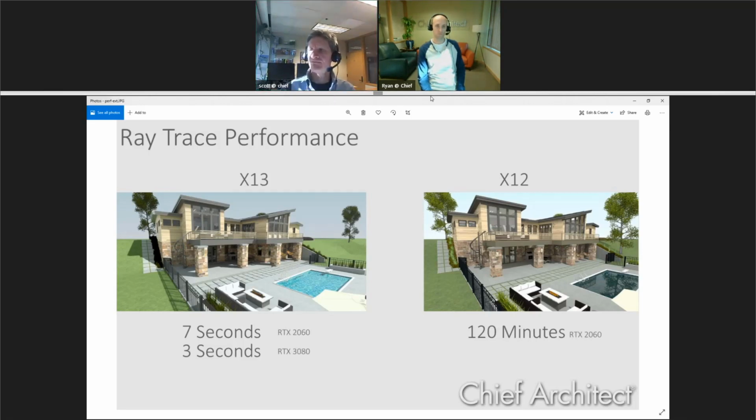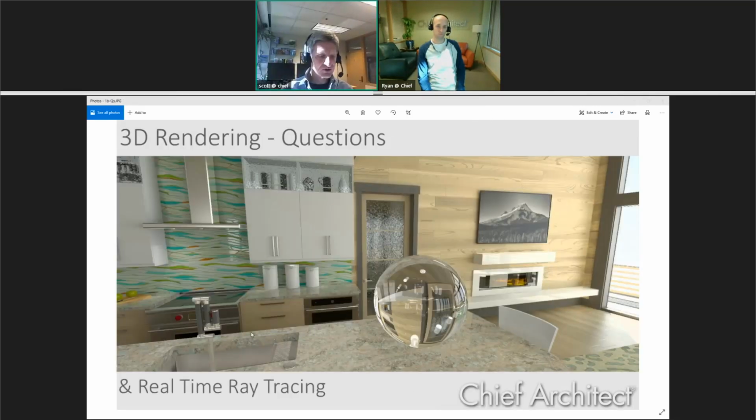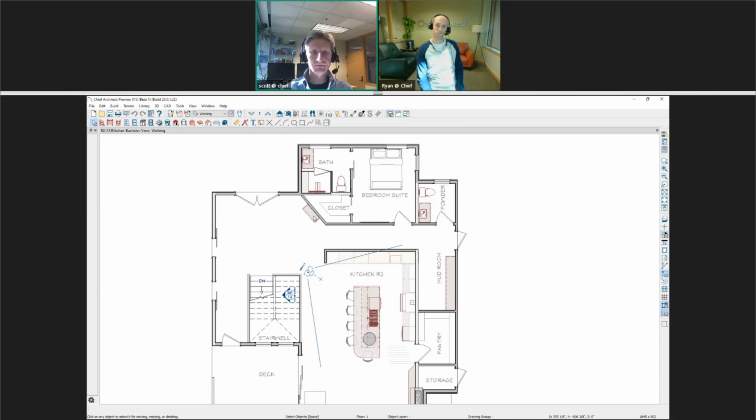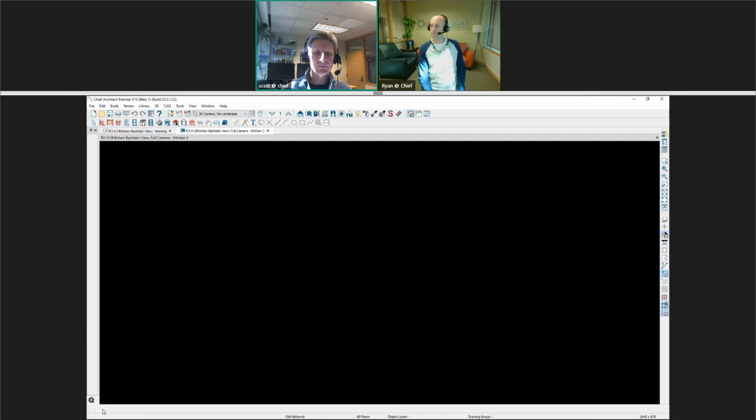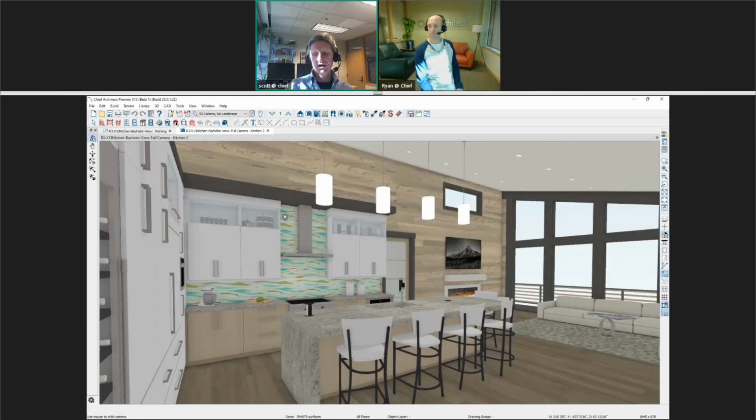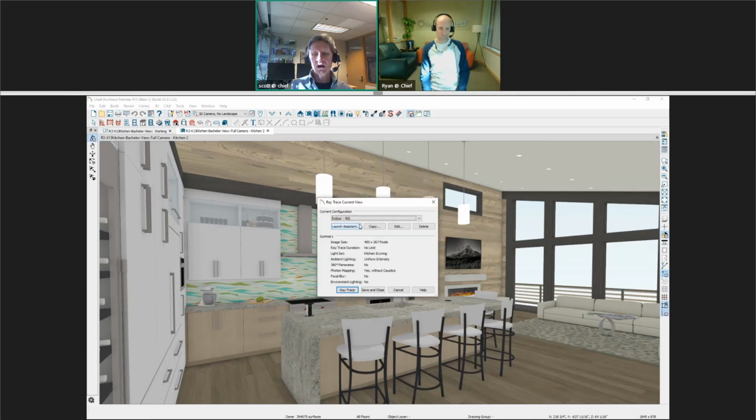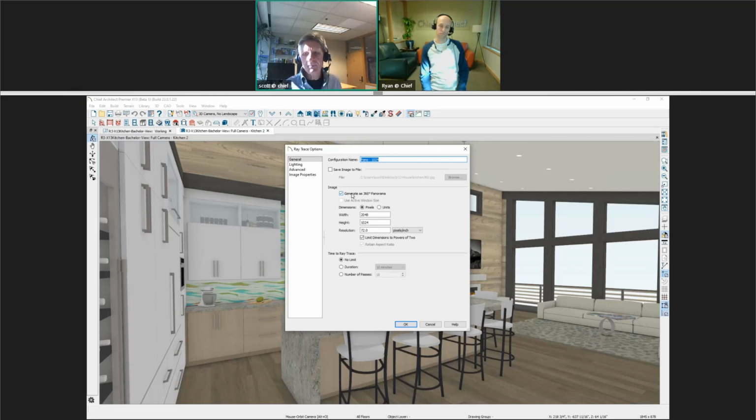Well, the best thing to do is when you actually set up your scene. Let me just open up a camera in here. There we go. A lot of times when you grab a camera and you open it up, let's go ahead and pop this open. And let's say you're going to ray trace this scene in here explicitly. When you click the ray trace option, you can go through, and I actually built a specific panoramic ray trace. Let's just use the smaller one. And you go in here and you click edit. There is the option to generate this as a 360.